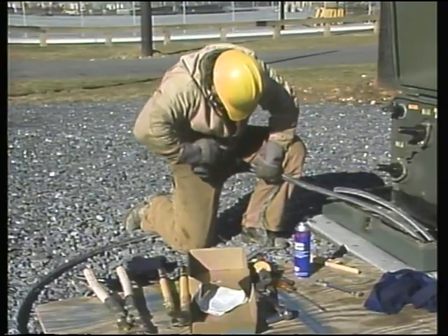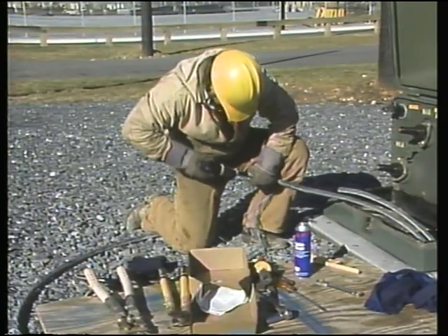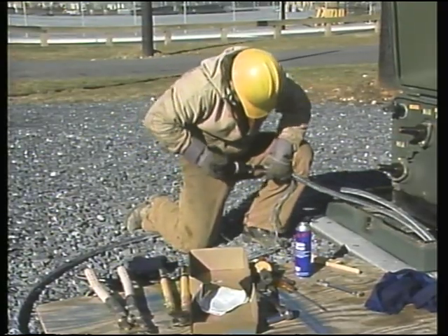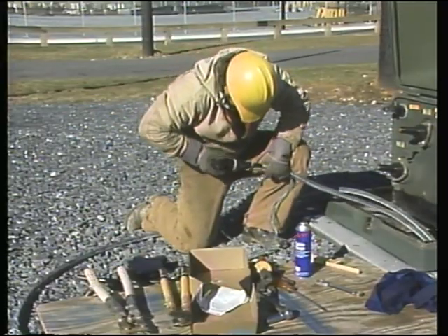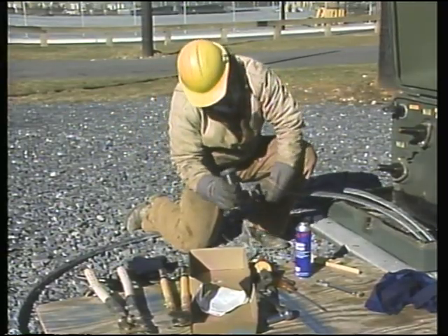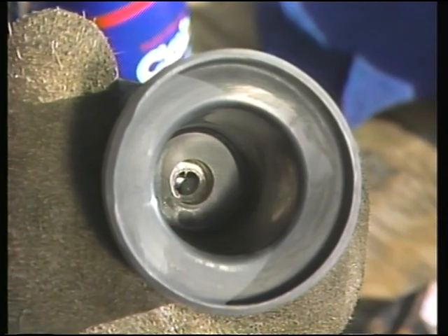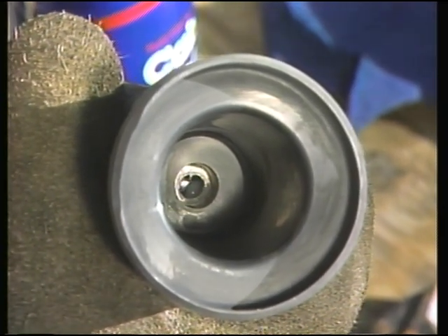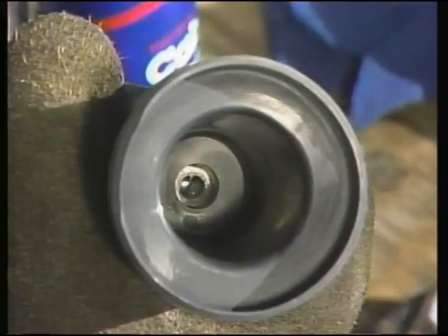He pushes the elbow termination onto the cable so that the connector eye is facing the bushing cavity. The bushing cavity is where the elbow makes contact with the equipment. By looking through the bushing cavity, the workman can see when the cable is fully inserted into the elbow.